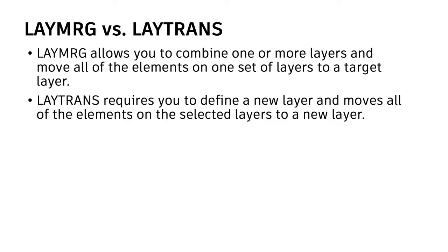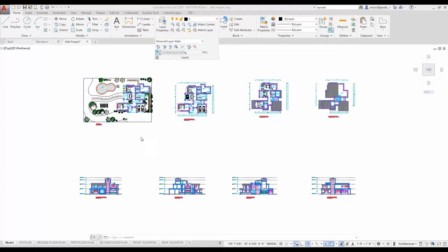LAYTRANS requires you to define a new layer and moves all the elements on the selected layers to the new layer. Both commands purge the drawing of the unused layers, the layers that have been depleted of elements.